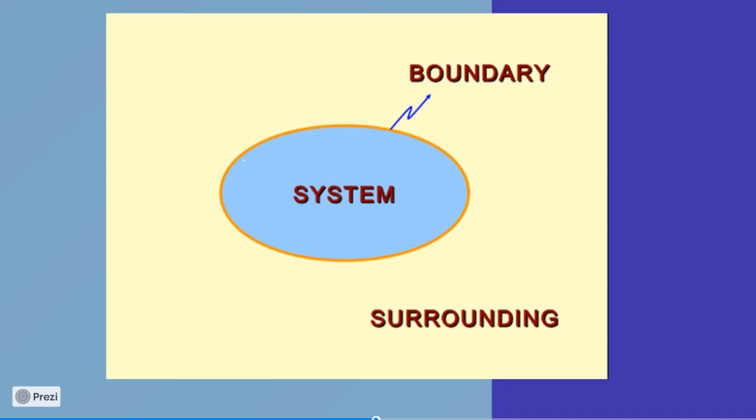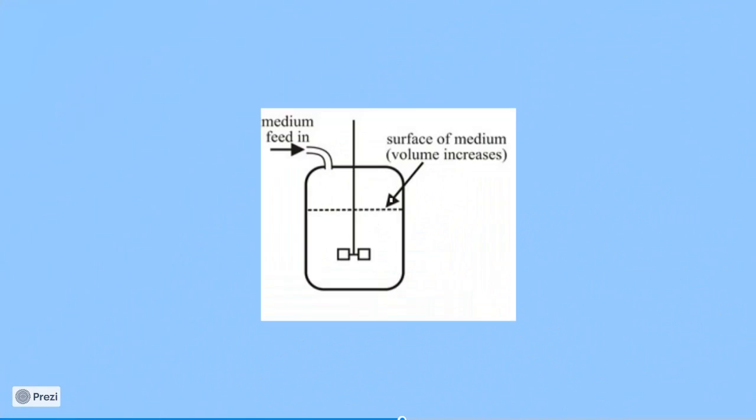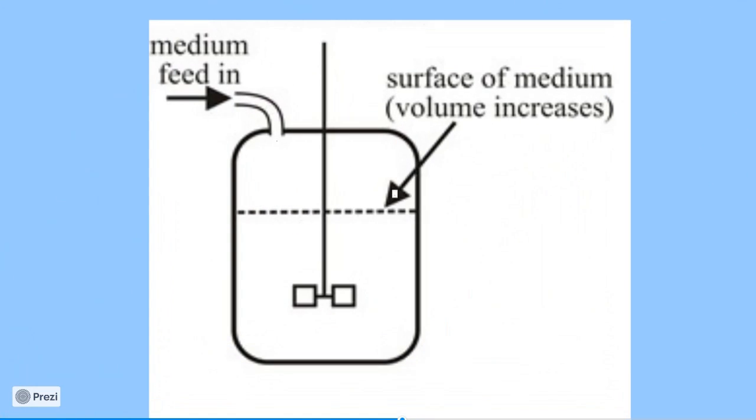The fed batch system can also be considered a semi-batch system where there might be periodic inputs into the system. The culture materials are fed continuously to a batch system and the process is allowed to proceed, wherein in a fed batch cultivation system, the volume of the medium increases in due course of time. Semi-batch operations are carried out in which one of the reactants is fed continuously, or one of the products is removed continuously, or all the reactants are added continuously.